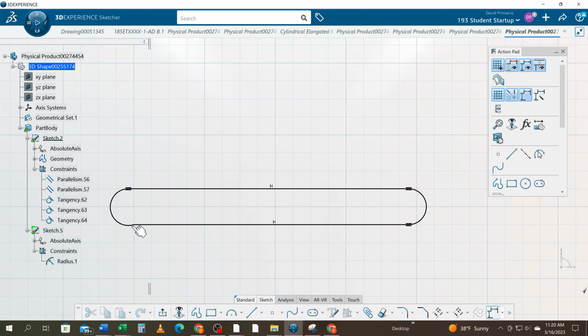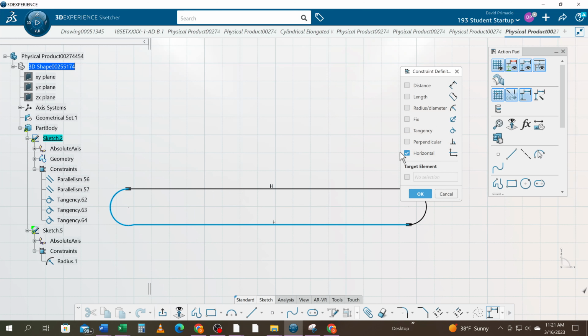See how this one, you can tell it's not tangent, and it's a common problem in production when people are trying to machine this. The NC programmers are trying to create a machine. They got something like this, they can't build that. It's not something that you want, but poor design all starts in the sketch. So you got to make sure that your sketch is correct.